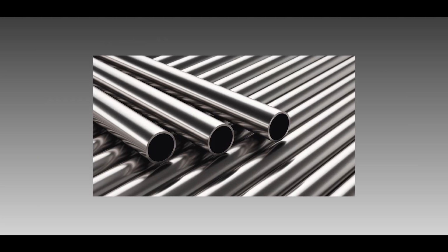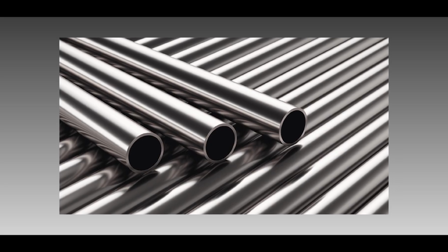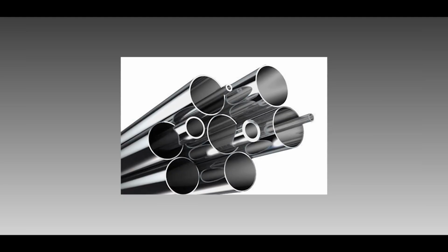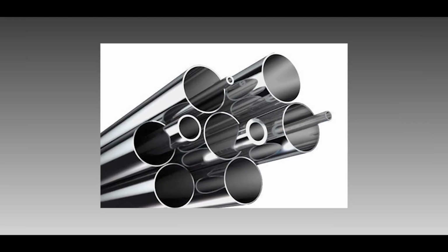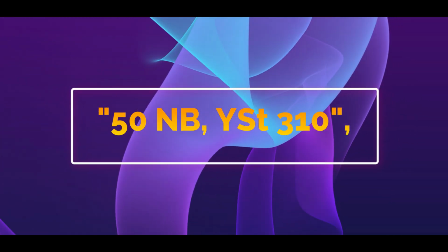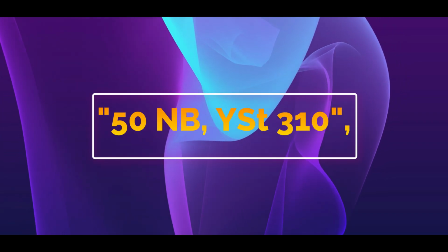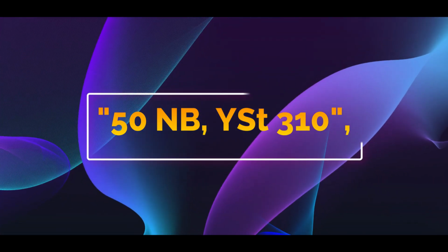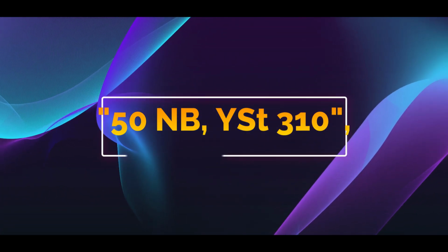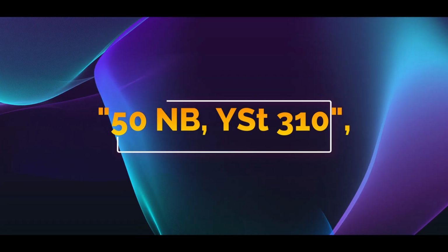A complete designation includes both the nominal bore and the grade of the material. For instance, a tube might be designated as 50 NB YST 310, which means it has a 50 mm nominal bore and has minimum yield strength of 310 megapascal for that grade.